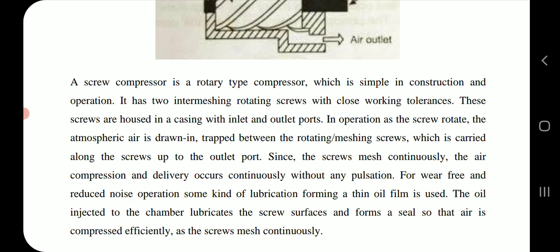For wear-free and reduced noise operation, some kind of lubrication forming a thin oil film is used. The oil injected to the chamber lubricates the screw surfaces and forms a seal so that air is compressed efficiently as the screws mesh continuously.